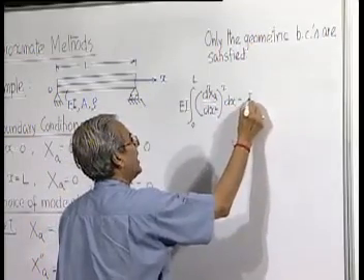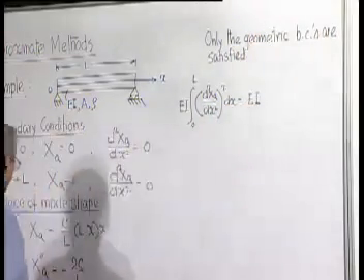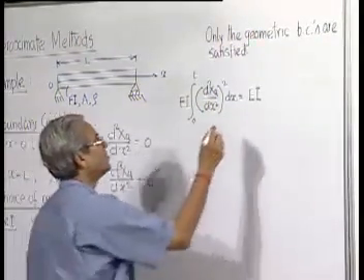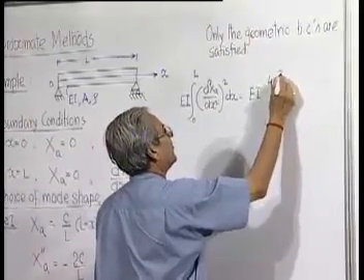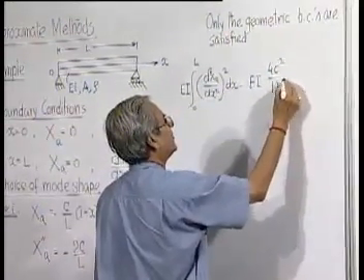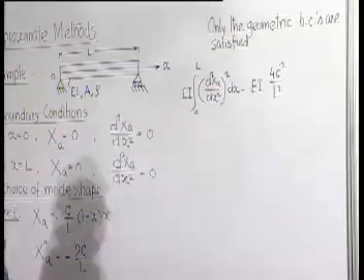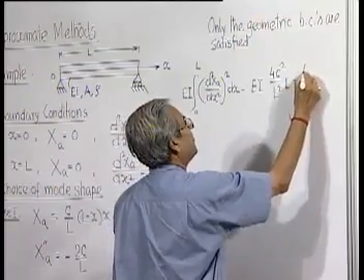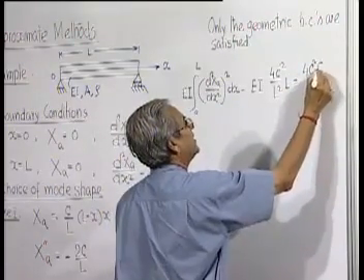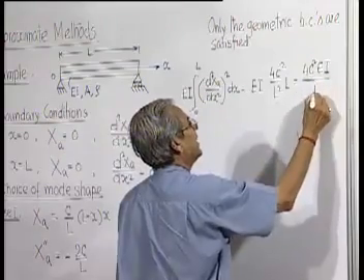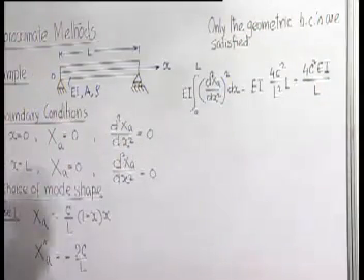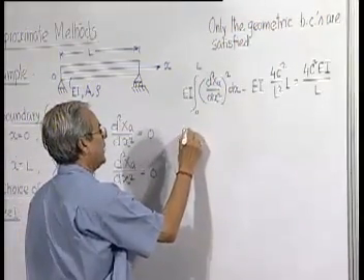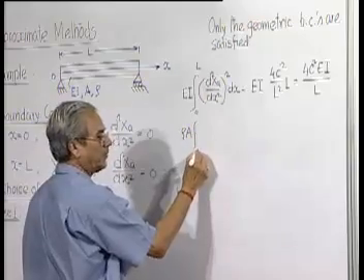This is equal to EI into, now d2X by dx square is minus 2c by L. If we square it, what remains inside is simply the integral from 0 to L of dx, which is nothing but L. That is 4 c square EI by L, the numerator. The denominator is rho A, again constant because it is a uniform beam.